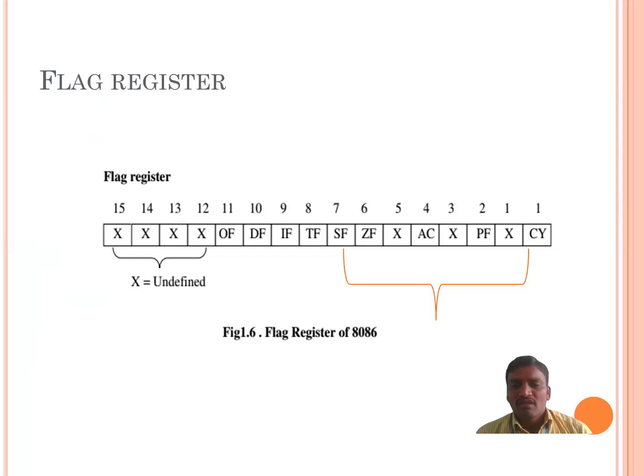So that's why all the internal ICs available in this microprocessor are 16-bit only, except the address bus size. Here that is a 20-bit address size. Why? Because the memory capacity of the 8086 microprocessor is 1 megabyte of memory. In order to access each and every memory location, it requires 20 address lines. So that's why the address bus size is 20 bits.